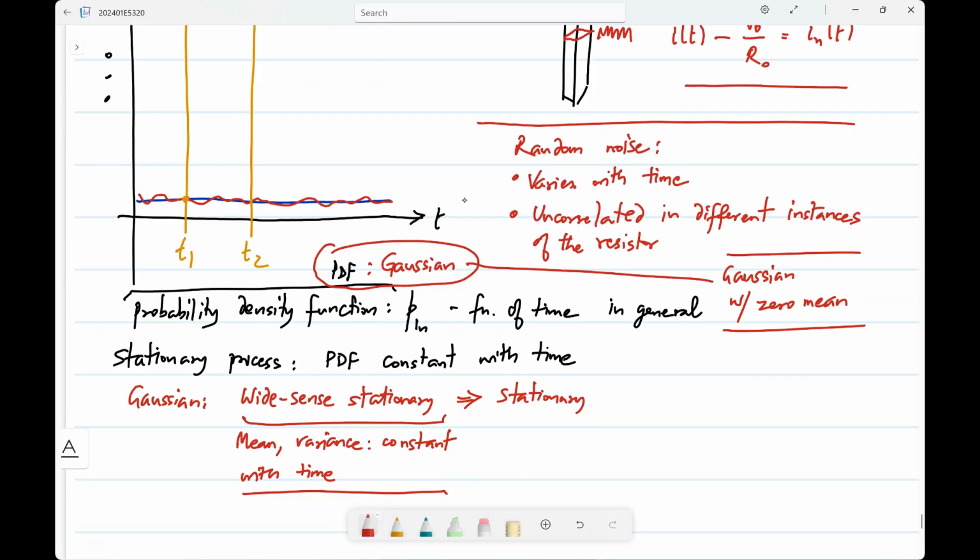Now, because noise is time varying, see earlier also we dealt with randomness. Then we didn't have to worry about all this. We just had to do the analysis for the signal. And after that, this variance stuff was just very straightforward. Here, by the way, in mismatch also, if you are looking at time varying signals, the small signal source corresponding to mismatch error could be time varying. But anyway, now we need a frequency domain description of these random signals so that we can go forward with the calculations. Any questions here?